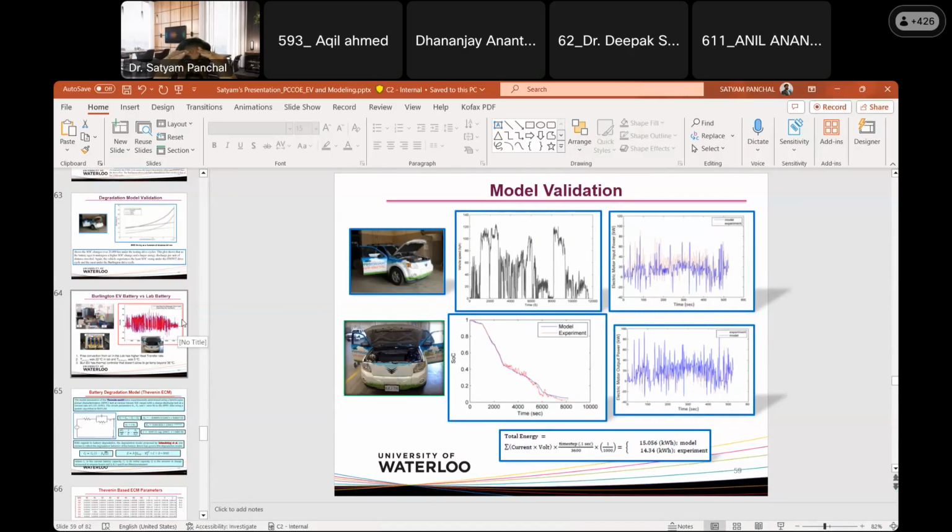So again, it depends on vehicle to vehicle. Plus, it depends on the type of battery. But if you are talking typically about the Ford company, they are using cylindrical cells for this battery. If you have a similar battery in a different vehicle, let's say Hyundai, if you have a similar 18650 with almost the same specifications, you can use those cell parameters, called ESS, energy storage system parameters. But for vehicle mass and a little bit more, you have to modify those parameters based on the vehicle dimension, mass, and a couple of other things. But yes, if you have a different vehicle with the same battery, you can use a couple of parameters based on my published paper.